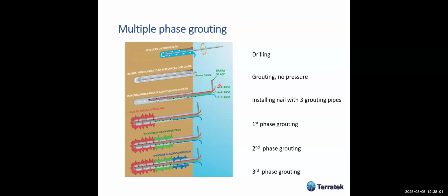The other thing that we are doing, I'm going to talk about a little bit about that. When you have an inclined slope, let's say 60 degrees or less, in most cases, we don't need the plate, and we just bend the steel bar like this, and it works. So we're going to discuss this later.